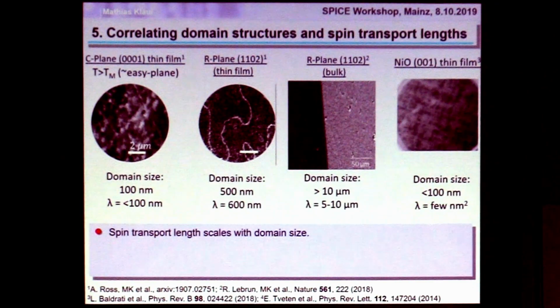How about strain actually? The nickel oxide, cobalt oxide, they are all heavily strained as bulk crystals. Yes, very heavily. I think the thin films probably suppress it, but it should nevertheless be there somehow. I think the difference is that in thin films you get much more local strain because you have misfit dislocations at the growth. And at these kind of grain boundaries, even if they're highly oriented, I think that's where the strain is, and I think this is what gives you the small domains.